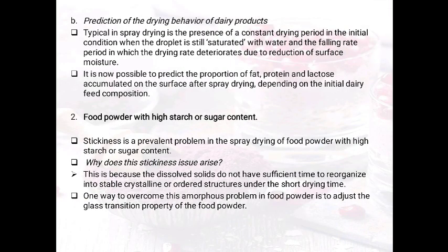Prediction of the drying behavior of dairy products. Typical in spray drying is the presence of a constant drying period in the initial condition when the droplet is still saturated with water, and the falling rate period in which the drying rate deteriorates due to reduction of surface moisture. It is now possible to predict the proportion of fat, protein, and lactose accumulated on the surface after spray drying, depending on the initial dairy feed composition.